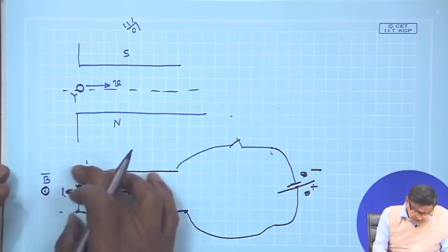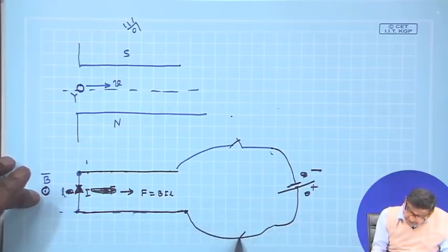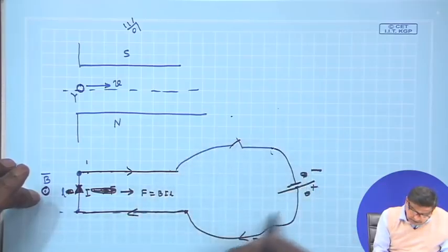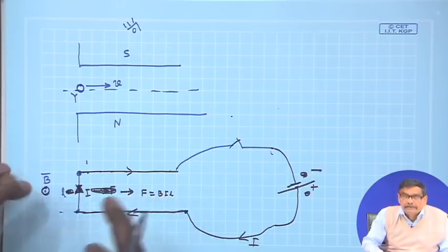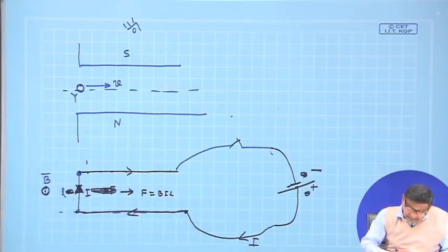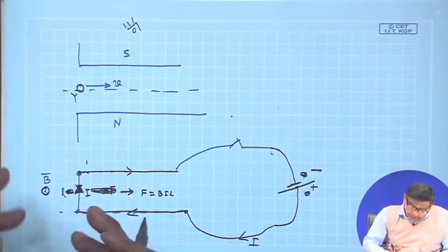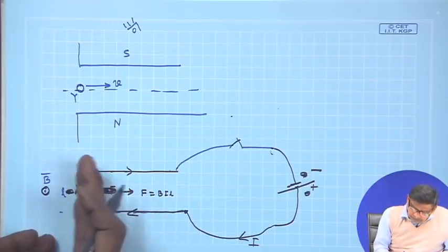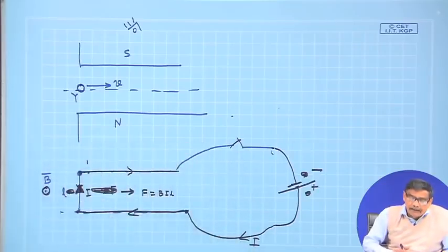Therefore, conductor was stationary. In presence of a magnetic field, you pass some current I, it will flow like this through this flexible wire, it will complete its path and then it will experience a force BIL. Now, as it starts moving, what happens if you apply some force to a mass, it will accelerate. So, it will go on accelerating, velocity will change, but anyway it will move with a velocity.